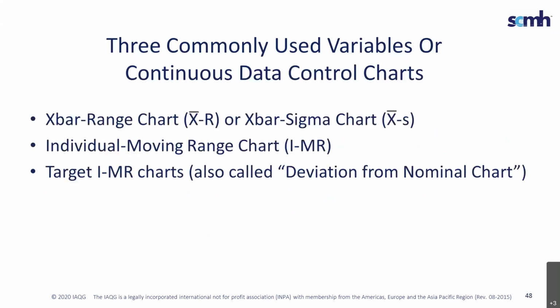Typically, I use an X bar S, an IMR chart. By the way, you can also use target IMR charts when you have features that are very similar for very similar processes, and overlay them on a deviation from a nominal chart. Just some top tips for charting.